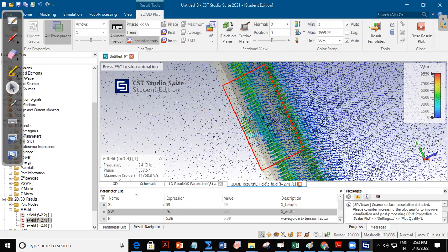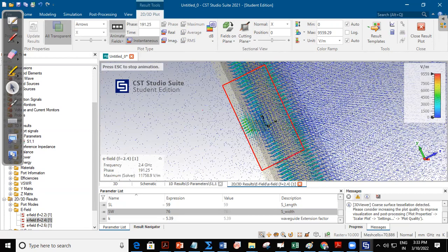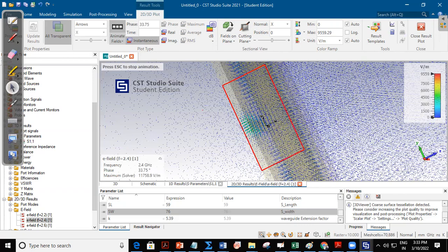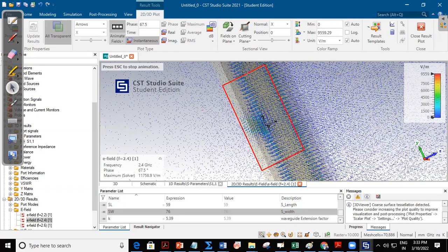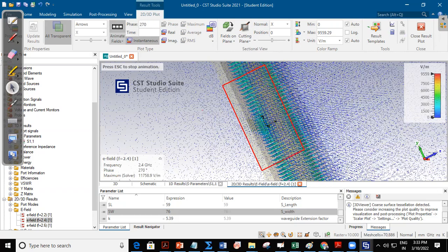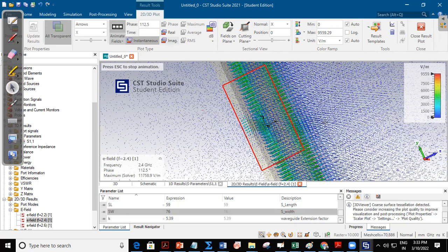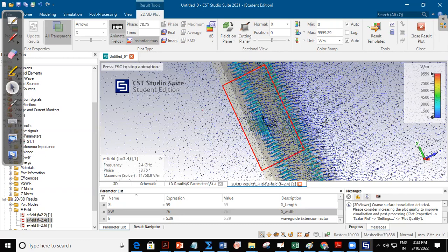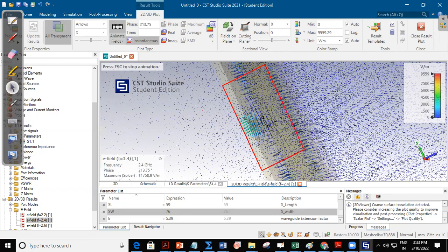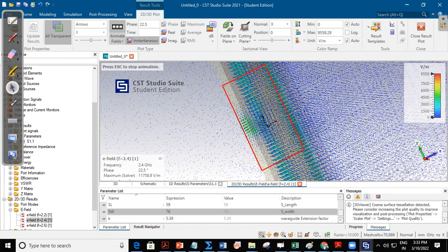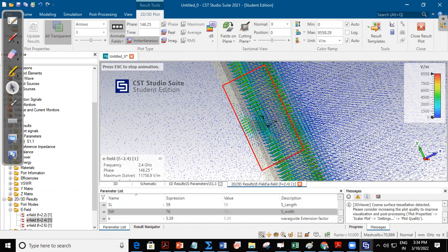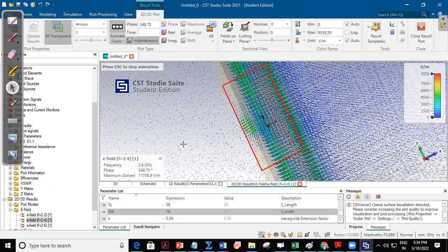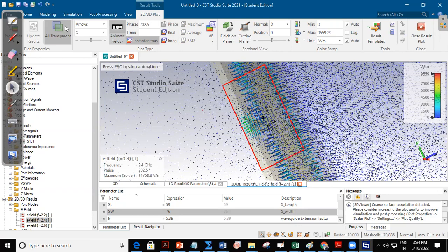As it works as a ground plane, you know it's a resonator cavity. The upside and downside are working as perfect electrical conducting walls, and the perfect magnetic walls from the other side. So we can see the radiation patterns which are there. It is achieved at the resonant frequency, and the radiation occurs at the side because of the current distribution in the cavity's wall, a top and down metal structure.